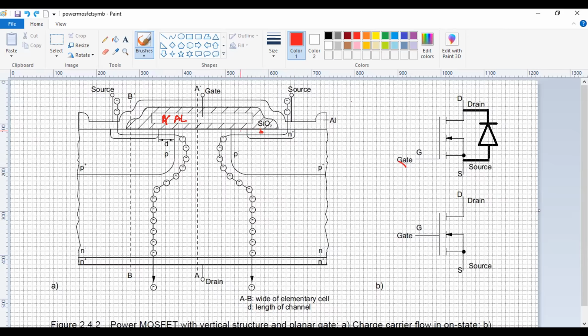And so what was done before with the MOS capacitor, the idea is basically to create a channel. That line shows where we'll create that channel. I want to create a channel so that I can connect the drain with this source. We create this small channel that has a few electrons, and that creates the connection so the electrons can now flow down like that.